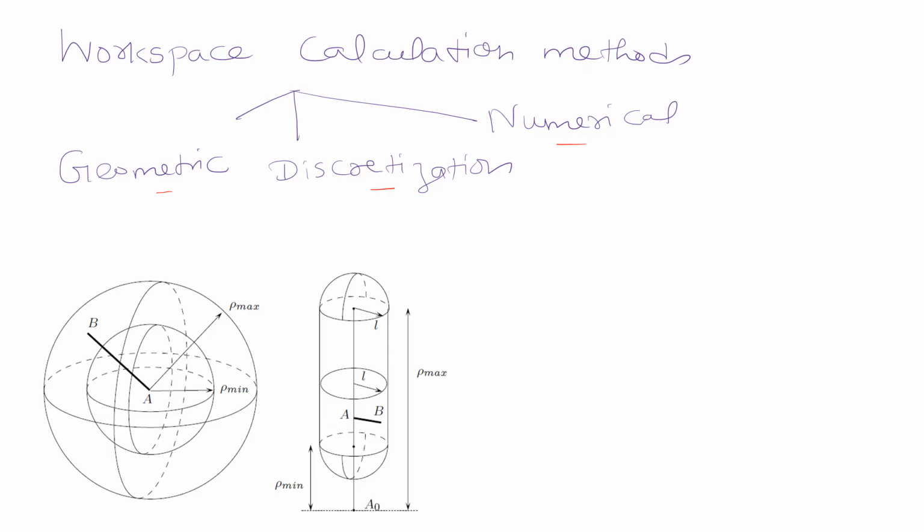In this method, we will be determining the boundary of the robot workspace geometrically. The principle is to deduce from the constraints on each leg a geometrical object, that is W_L, that describes all the possible locations of X that satisfy the leg constraint. One such object is obtained for each leg, and the robot workspace is constituted by the intersection of all W_L.